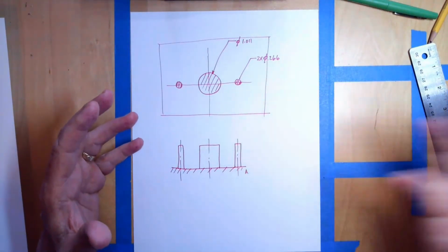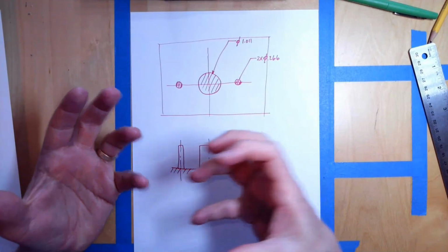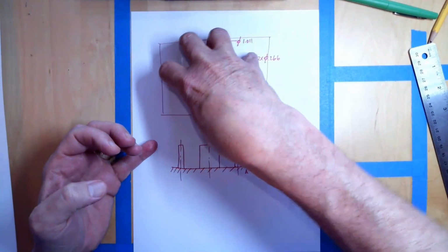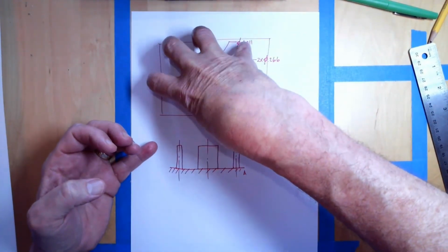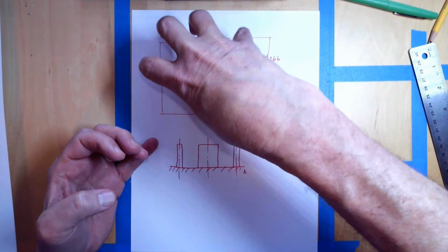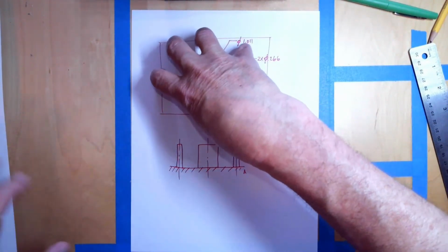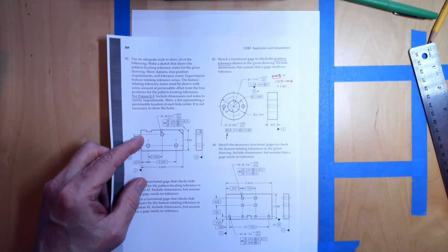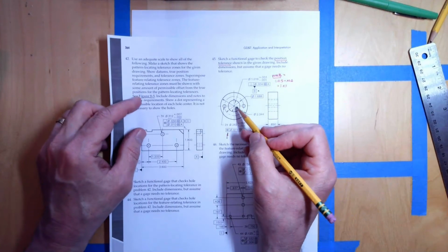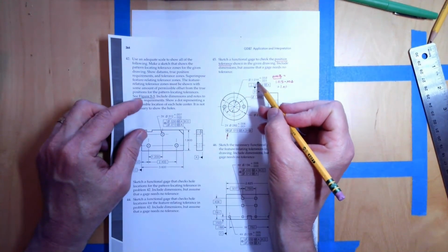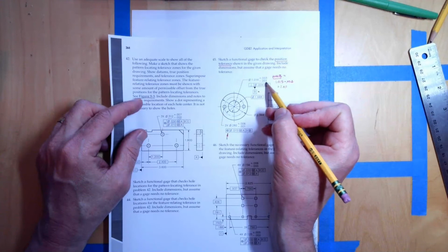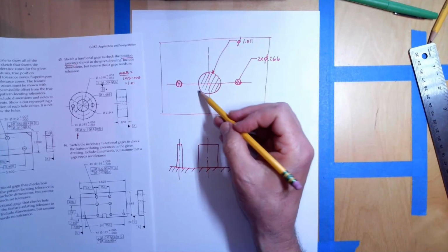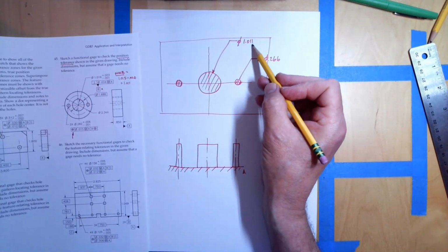We're going to take the part that we get out of the machine, when we're done milling it or whatever it is, we take the part out and we have to push it down on this. We have to get it to sit on this gauge. And if it sits on this gauge, then it's a good part. Now, let's just think about this for a second. So the part that we make, the center hole has a diameter of 1.016 plus or minus 1/1000. Okay? And it's going to go down on this 1.011 pin.